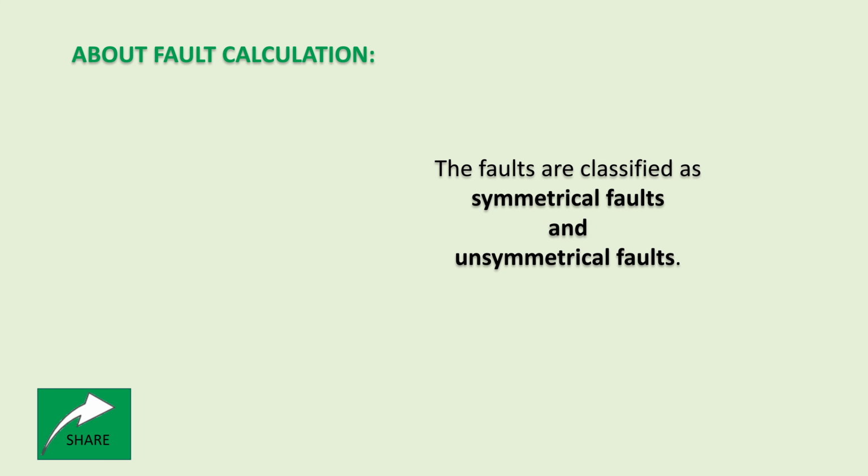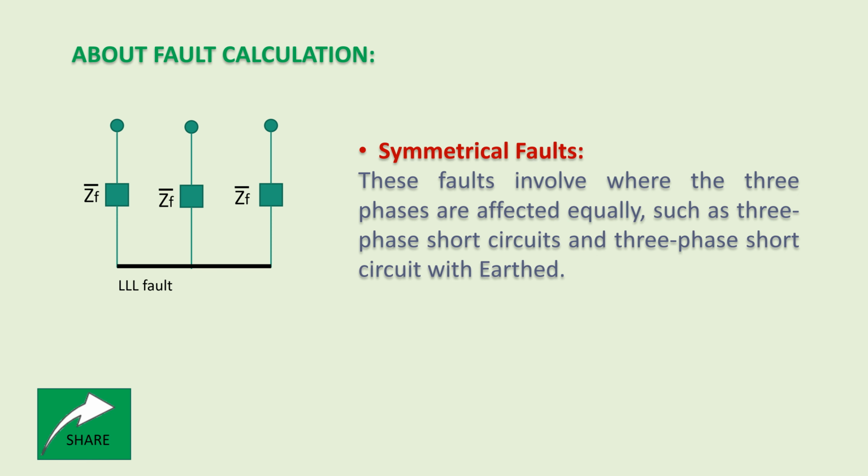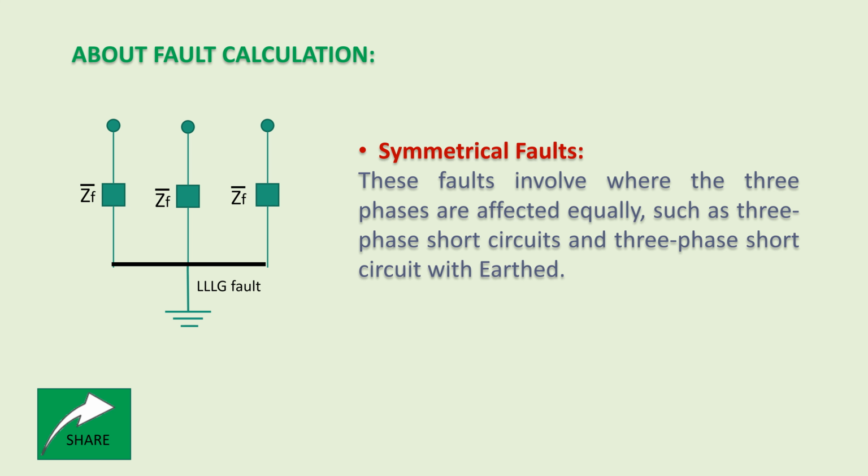The faults are classified as symmetrical faults and unsymmetrical faults. Symmetrical faults involve all three phases being affected equally, such as three-phase short circuit LLL and three-phase short circuit to ground LLLG.